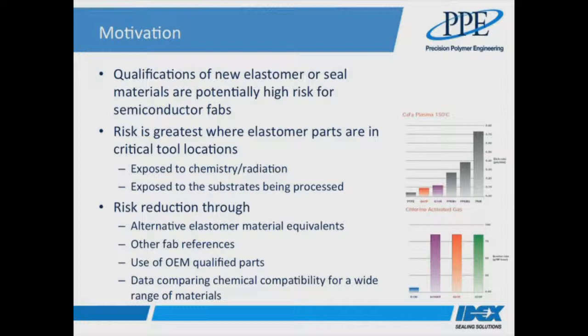The wafer sits in the chamber, and therefore anything in contact with the chemistry and in proximity of the wafer, again, including seals and O-rings, becomes a critical component, which is capable of contaminating the wafer. Now that contamination could be something obvious, such as a particle, or it could be something that has the capability of altering the electrical parameters of the device, or whatever product's being produced. These are also the sort of things that are either difficult or impossible to monitor in situ. And this means that multiple process passes can happen before anyone realizes something has potentially gone wrong.